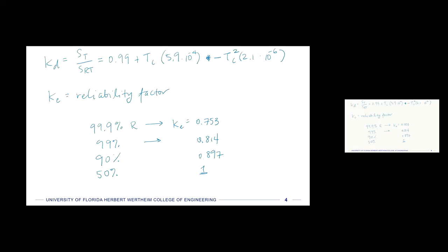So one exercise that I have my students do in EML5005 is I have them look at all these charts and these ranges, and I say, calculate the worst possible case scenario. So you're basically multiplying like 0.1 for Ka. Let me just go back here. Yeah, like 0.1 or 0.2 for Ka, and then maybe 0.5 for Kb. And then you keep going down from there. You're in torsion, so then you're at 0.6. You're at high temperature, so now you're 0.5. And then high reliability, 0.7. And so you really drop your endurance limit exceedingly low.